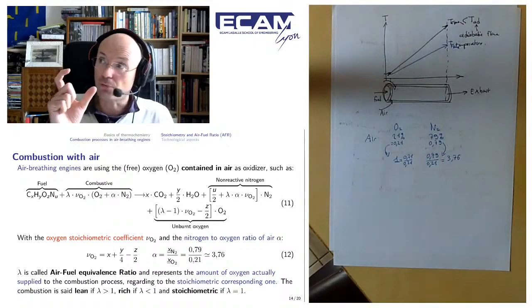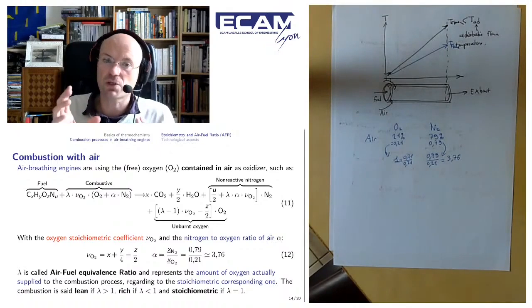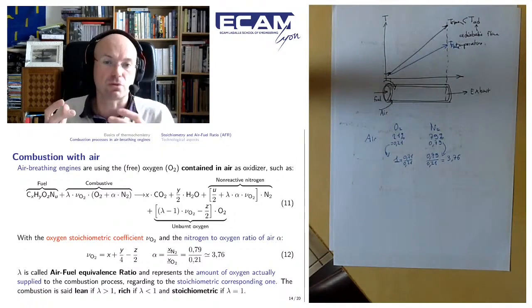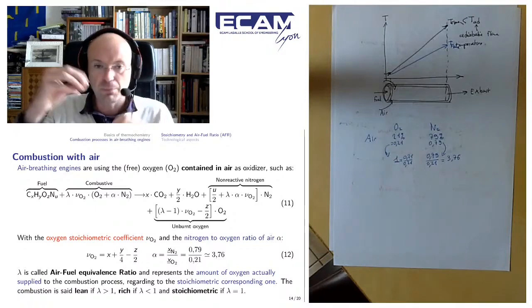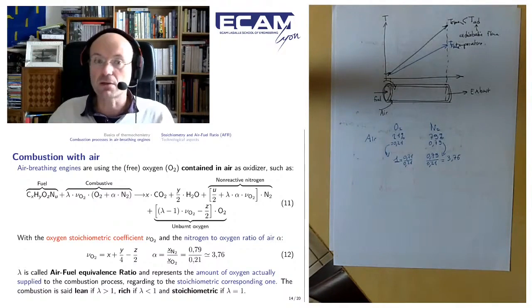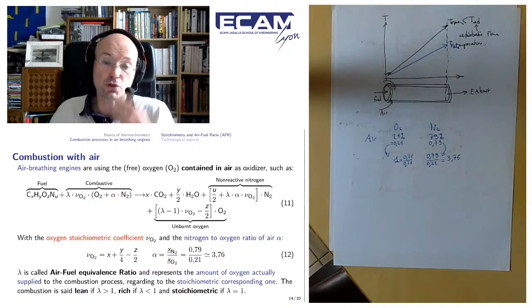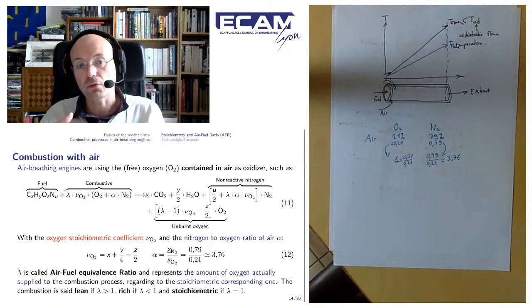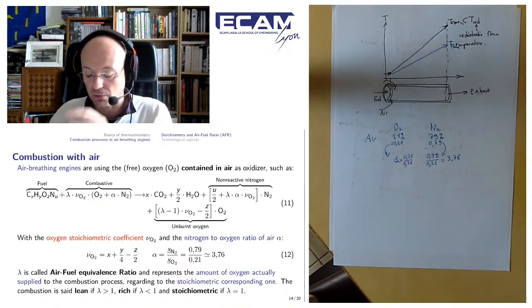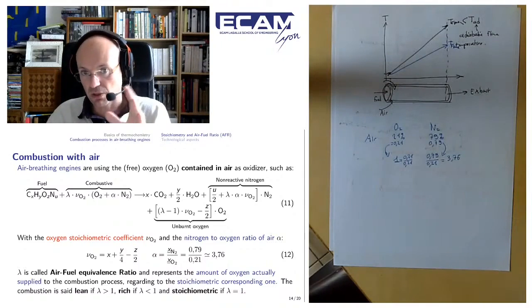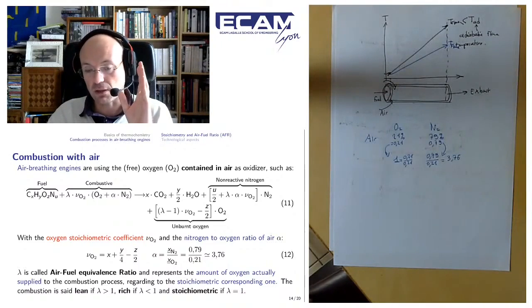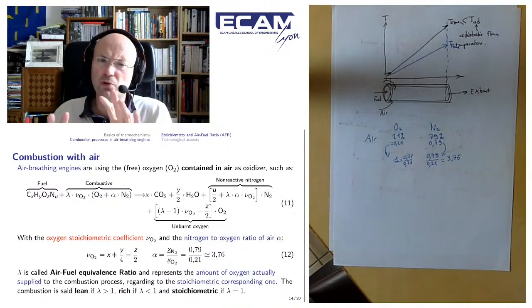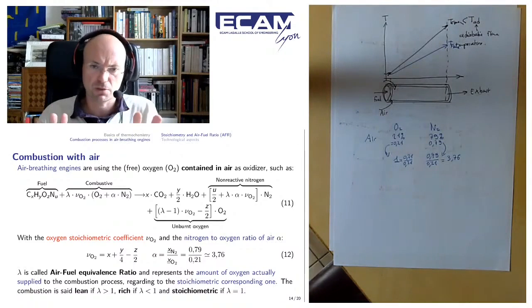And so, for a few seconds, or in the worst situation for some minutes, you have a rich combustion. Because the control strategy has not had the time to reach the goal, which is to maintain a specific ratio between air and fuel. In this case, it's rich, and it's really dangerous because it will produce a lot of pollutants, and we try to avoid this as much as possible.